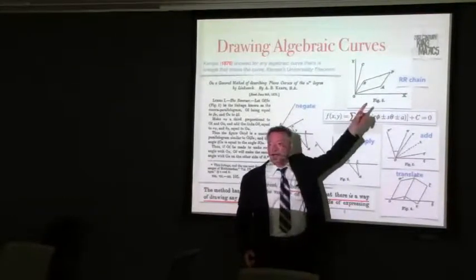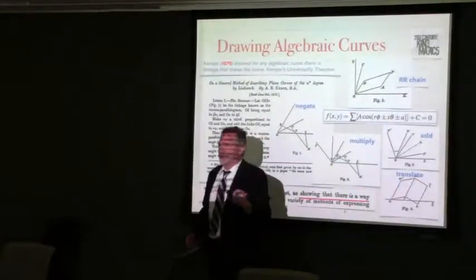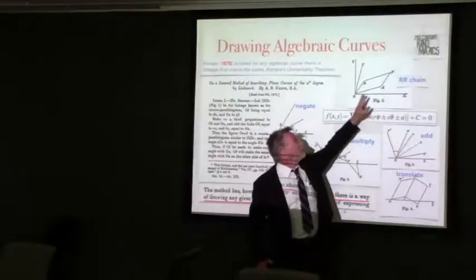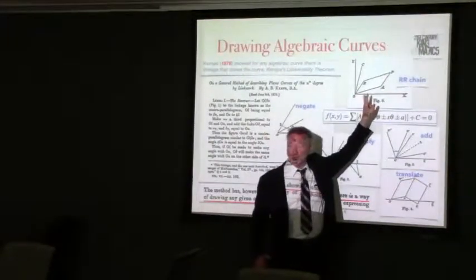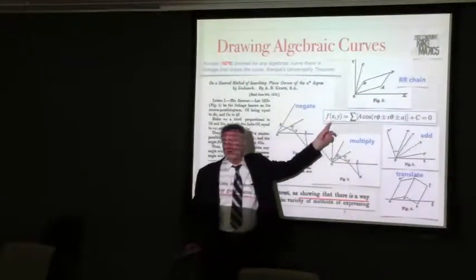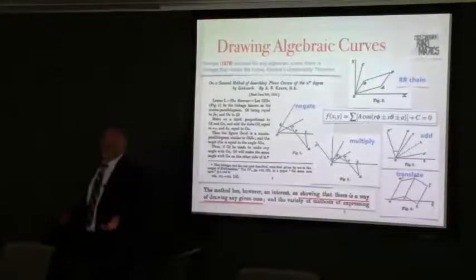We know that the endpoint of a 2R chain could trace any two-dimensional curve within its workspace. He said that I can use this equation to constrain these two joints of the 2R chain so that it draws this plane algebraic curve exactly.